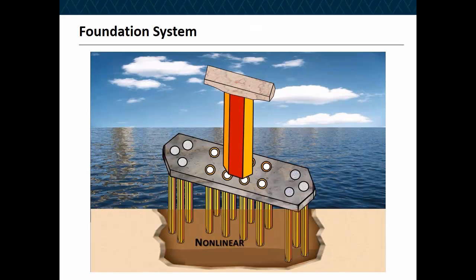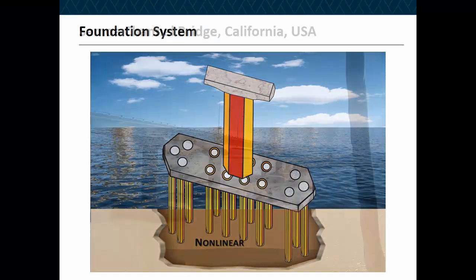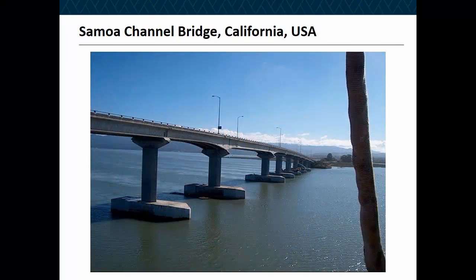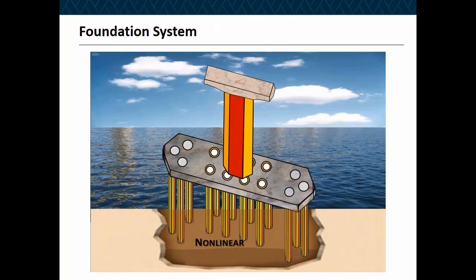The piles are about 40 feet into the ground, and they're about 50 feet cantilever above the mud line, all the way to the water surface, which you can see here. So these piles are almost like a cantilever sitting on pile caps, and the pile caps are above the water surface.